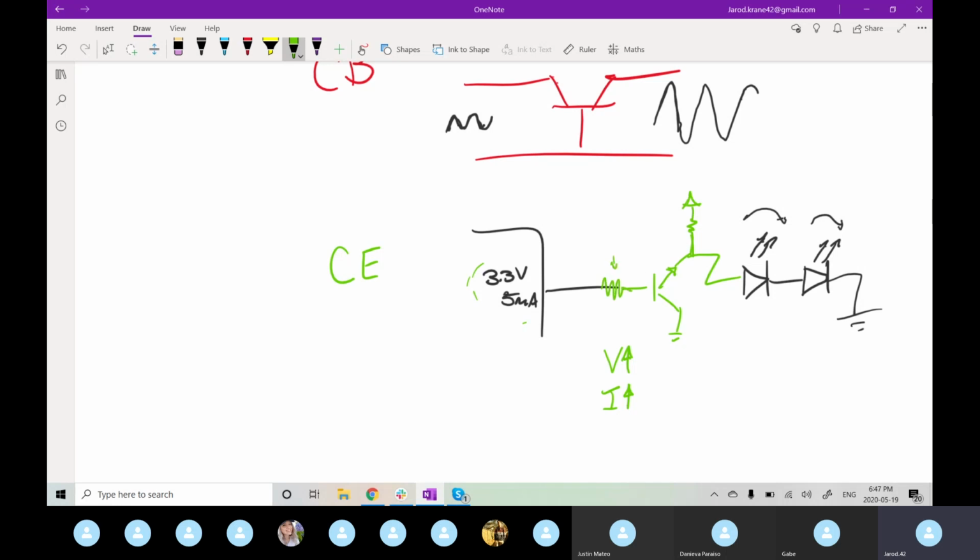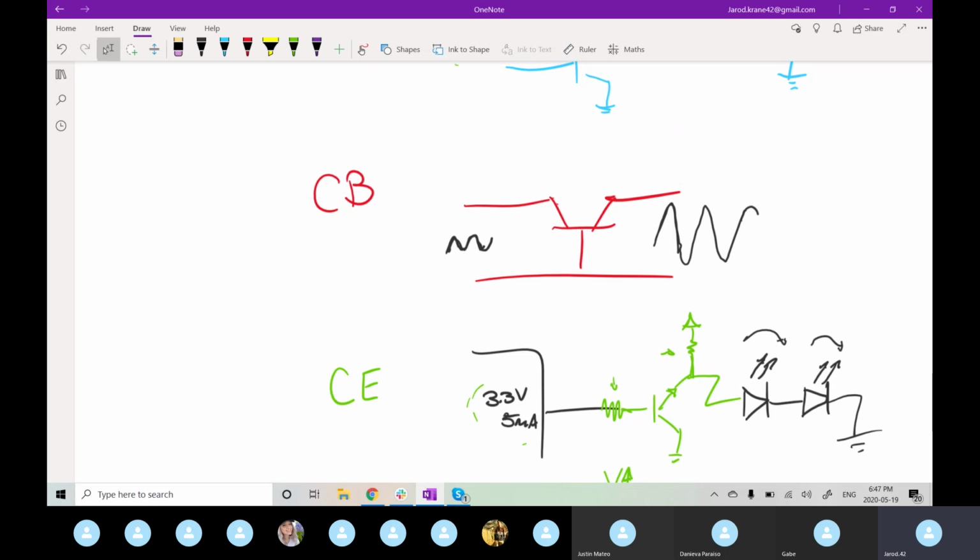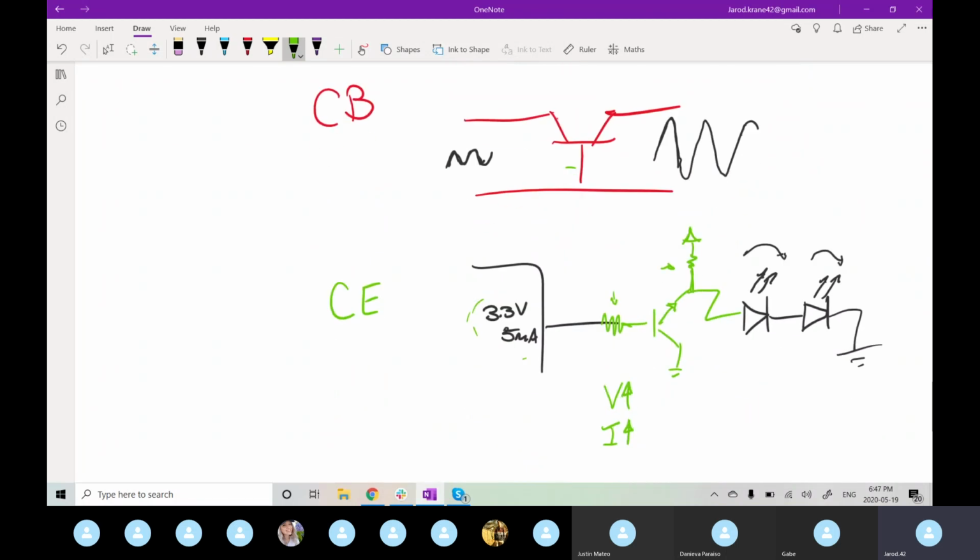So the input, the base resistor and collector resistors in one configuration compared to the other, you may be using more resistors, which will have their own losses, and that's what will potentially make one of these circuits less efficient compared to the other. But functionality-wise, transistor to transistor, it's all basically the same efficiency.